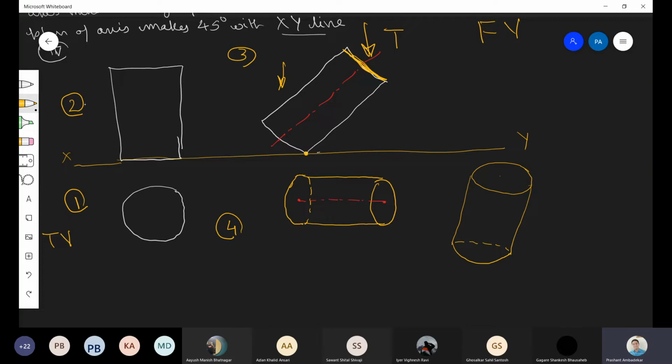And there is the axis here, and what is the angle the axis is making? It is making an angle of 45 degrees. Now how will you draw this? Again, pay attention here, the center axis and the generator. So what will we see? We will not see the axis, we will see only the generator, like this and like this. The same generators will be drawn here.